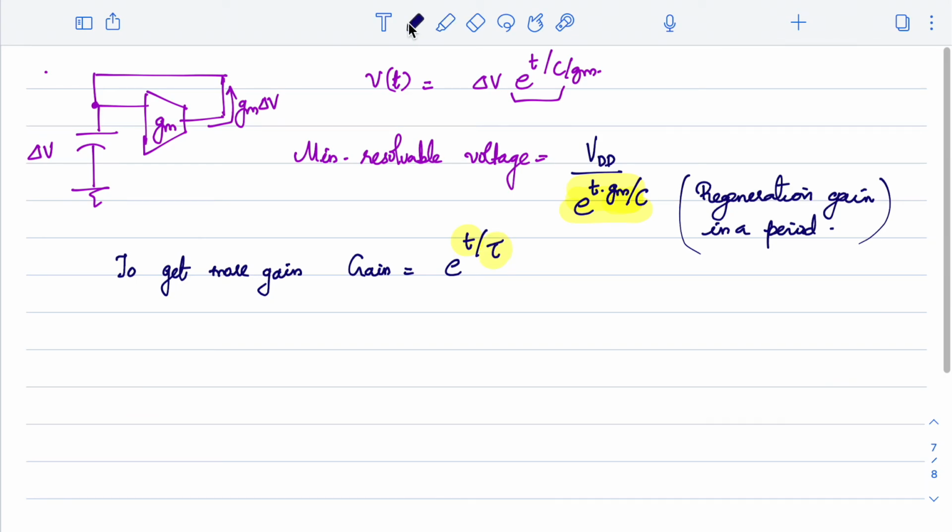When I say I should work for a longer time, in the sense I should wait longer for the decision to be made, which is not practically possible, because I cannot wait for days together for the circuit to make a decision. That is even decided by other factors of the ADC or the system we have. So generally we cannot wait for a longer time. What we can do is work on the time constant factor, so we can reduce the time constant tau.